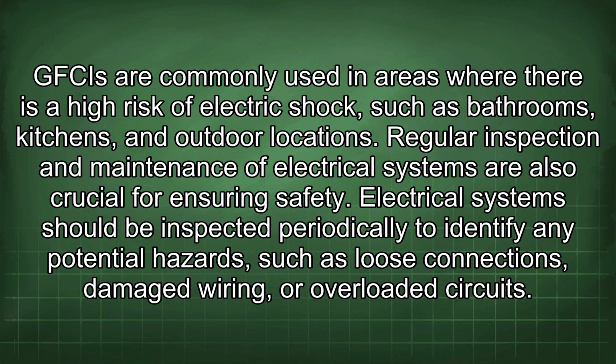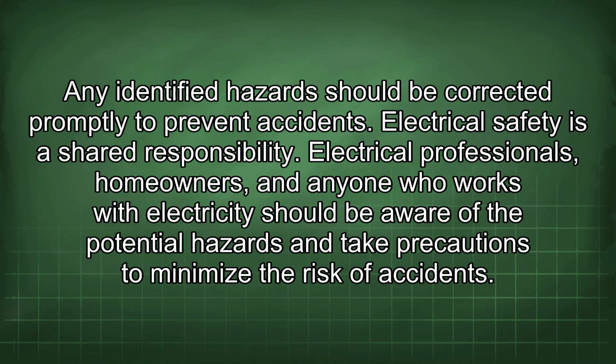Regular inspection and maintenance of electrical systems are also crucial for ensuring safety. Electrical systems should be inspected periodically to identify any potential hazards, such as loose connections, damaged wiring, or overloaded circuits. Any identified hazards should be corrected promptly to prevent accidents.